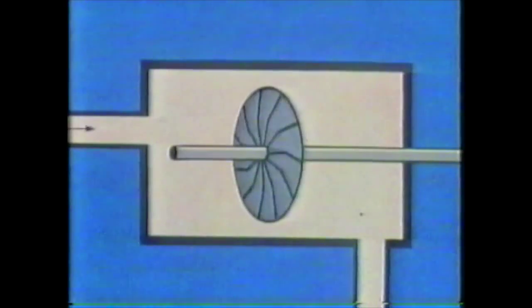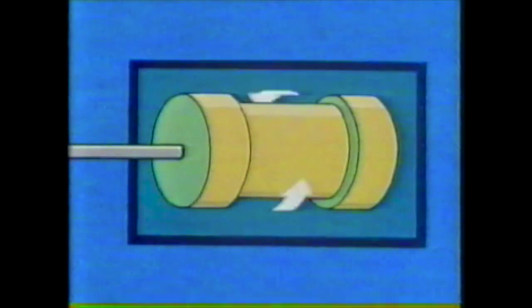This mechanical energy of rotation is turned into electrical energy by the generators. A big electromagnet, the rotor, rotates inside a system of coils, the stator, and produces alternating current, which can be sent out over the national grid system.